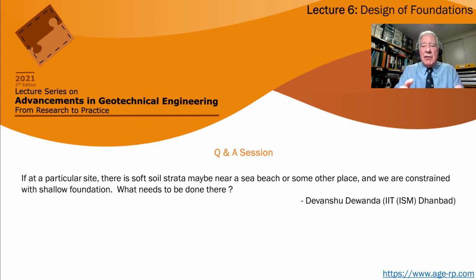If that doesn't work, then we need to go to a deeper foundation, whether it's a pier, a raft, or a more complete pile solution. That's just something we have to work out. But we always have a look at how far we can go with the most obvious, most sustainable and cheap solution, which is generally a shallow foundation.